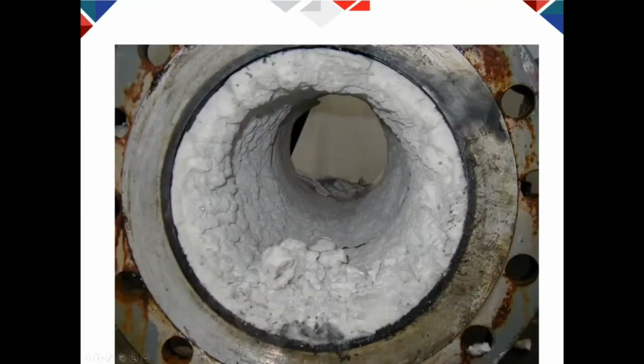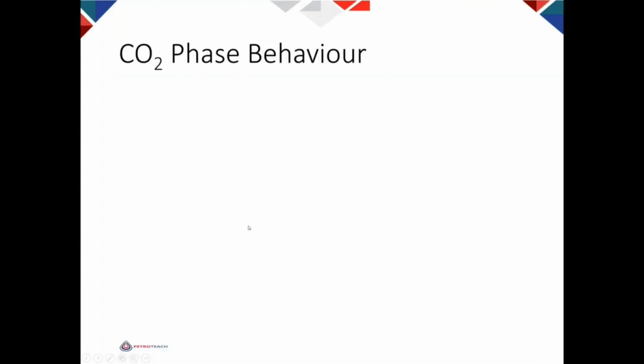But you can see that this is hydrate forming from water in the gas phase, because you see that homogeneous hydrate formation. So either hydrate forms from the gas phase, or the gas velocity, which is high, turns water into a sort of mist. And that mist, the water droplets, basically do not form a liquid phase at the bottom of the pipeline. So hydrate is forming like this.